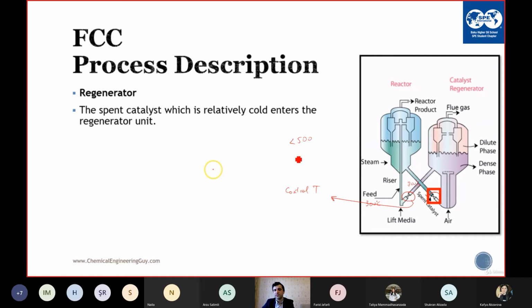If the temperature, let's say, is above the 120 Celsius, then we close the control valve a bit, allowing the temperature to decrease. And this one is the pressure controller. It controls the pressure at the top. How?